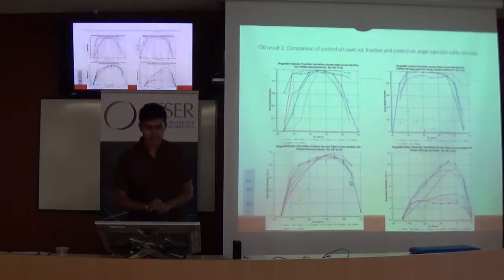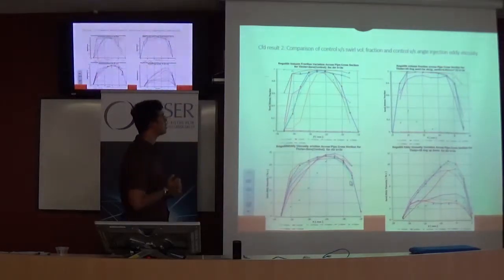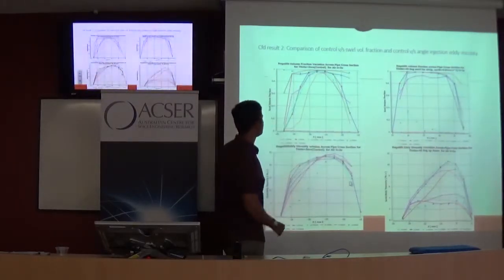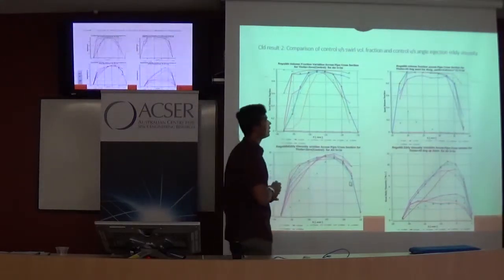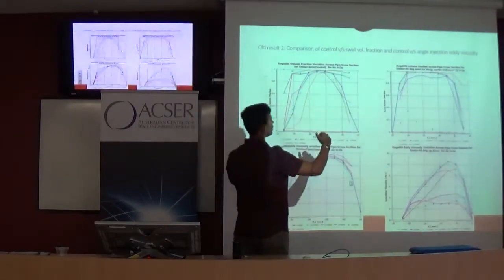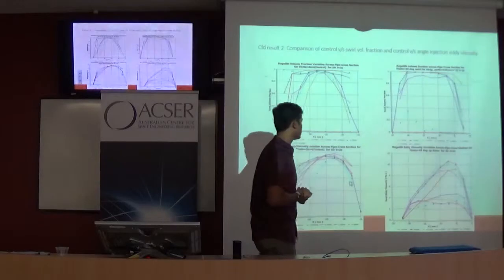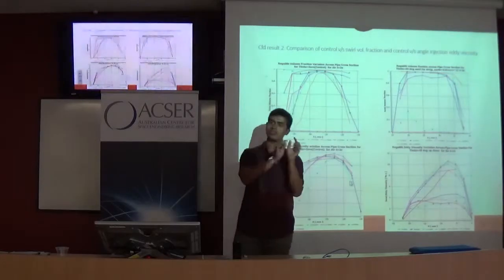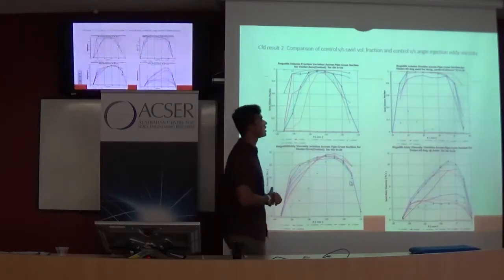The first top left and right graphs give you volume fraction distributions. If you're looking at the side view of your sample tube, from one end to the other end, it gives you the distribution of the sand particles. It was seen that the swirl assisted flow led to a much wider distribution of the volume fraction as compared to the case when there was no swirl. This is beneficial for us. It allows more regolith to move per, say, square millimeter of your pipe length, and eventually leads to a higher capture of regolith.